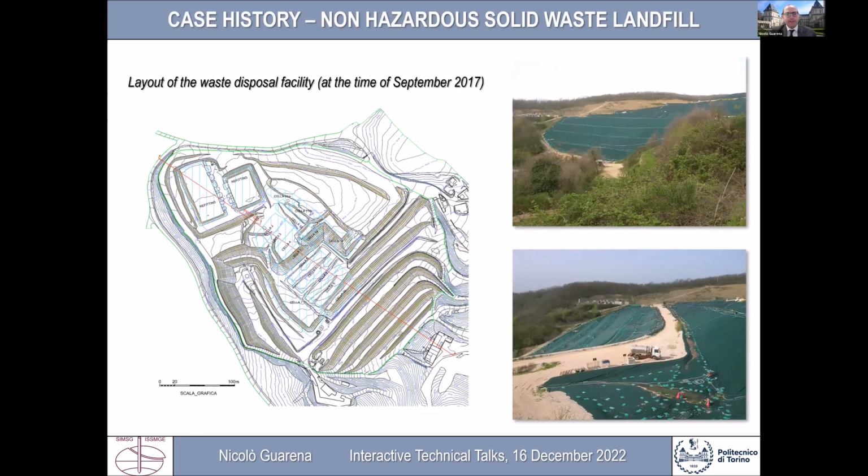The stability of landfills can be further threatened by the morphological conditions of the construction. This latter problem is particularly severe in those countries like Italy and Japan as well, where the high density of population and the numerous seismic, environmental, urban, artistic, and archaeological constraints significantly limit the viable areas for a safe construction of waste disposal facilities. The case history of a municipal solid waste landfill located in central Italy and constructed over a sloping ground is here presented, as it summarizes all the stability issues that have been pointed out so far.